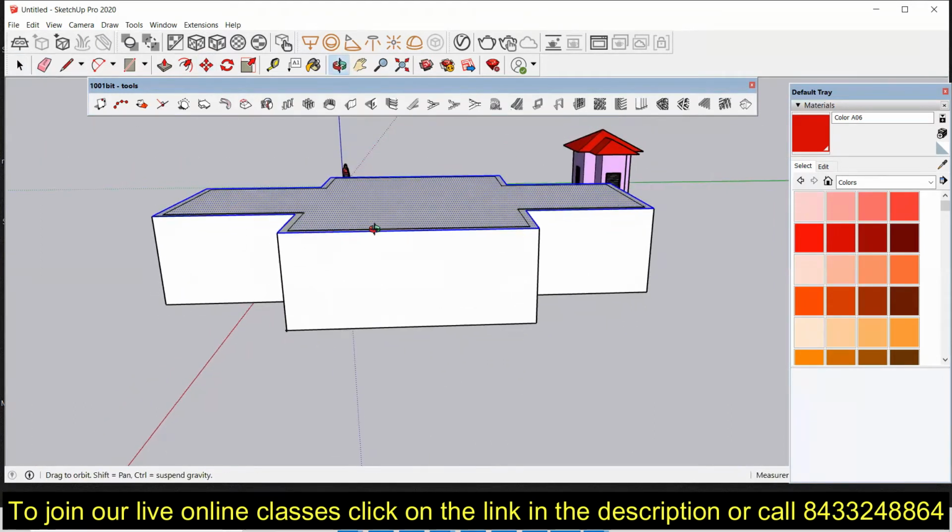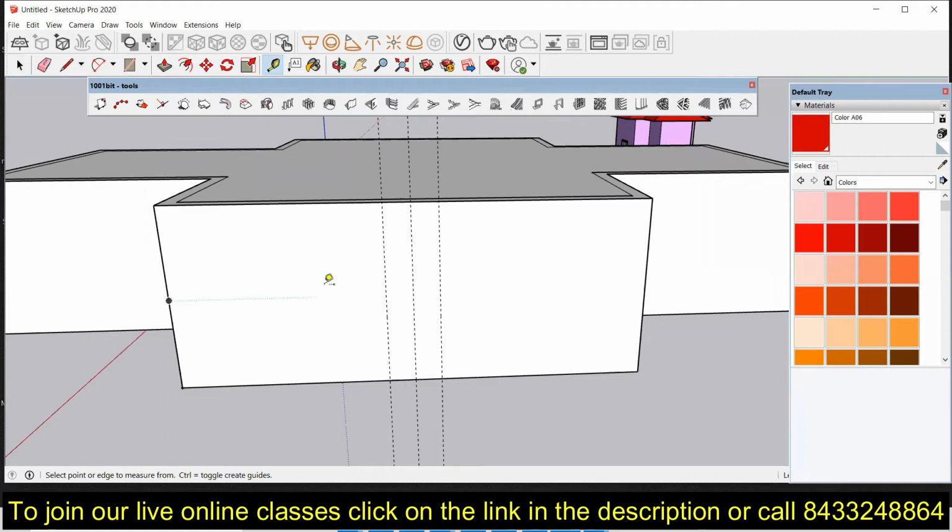Now what I need to do is create the doors. So first of all I will have to take the dimension of the door. For that I'm using the tape measure tool, and I will go to the midpoint of this one. Suppose I am willing to make a door of 3 feet, then I will take an offset of 1 feet 6 inches on both sides. So I can have the door of 3 feet. So let's make it 18 inches. Okay, now you can have a door opening over here.